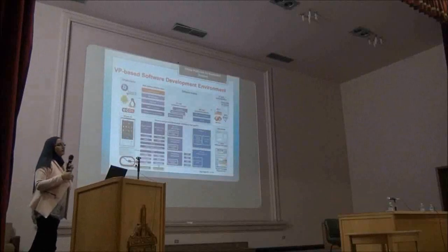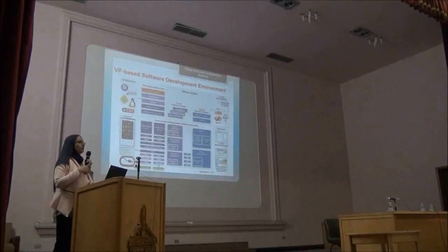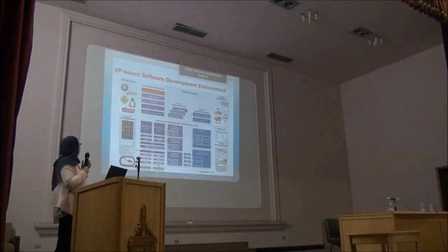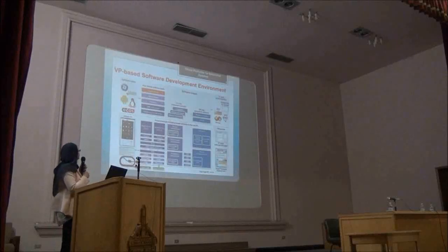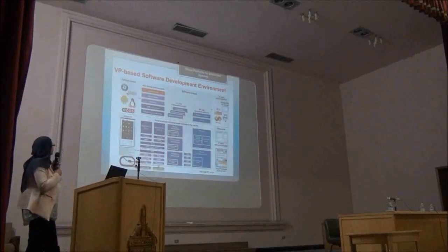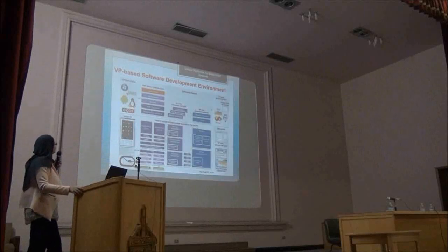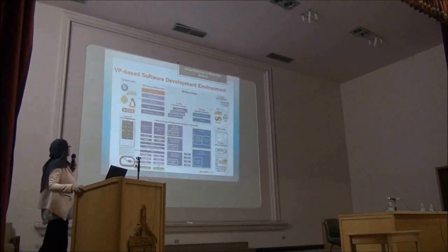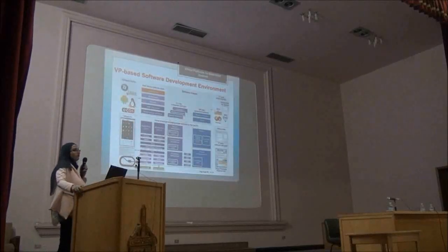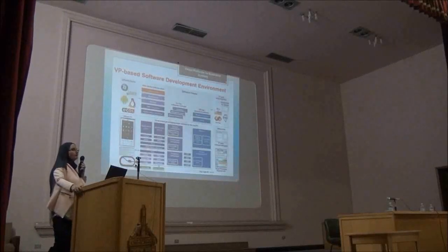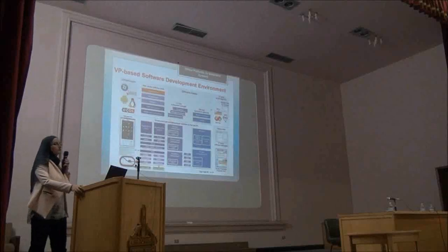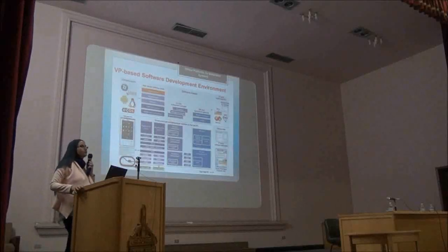Using SystemC and TLM, one can implement a whole virtual system with CPUs, with timers, with memory control unit, with analog to digital converter, with scan controller, with display controller, and then start to build the software image using the cross compiler he will use to target the real hardware.